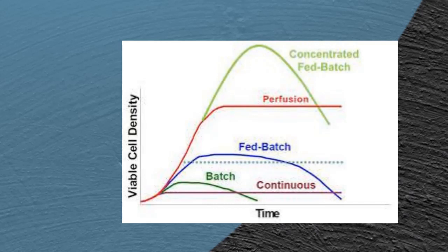In the batch system of cultivation, as the organisms grow, the substrate concentration dramatically decreases, and we can observe the presence of lag phase, log phase, stationary phase and dead phase. In the fed batch system of cultivation, when the limiting substrate concentration in the cell is about to run out, fresh substrate will be fed into the system, wherein we make the cells prolong in the log phase rather than switching into stationary phase, and the biomass concentration increases as long as the substrate is available in the medium.